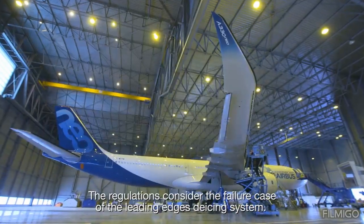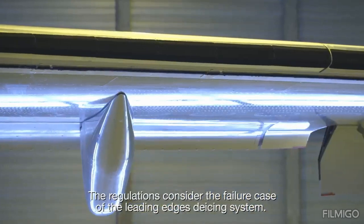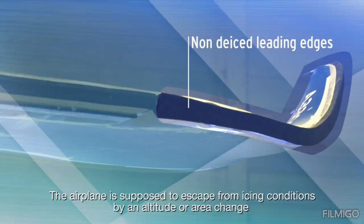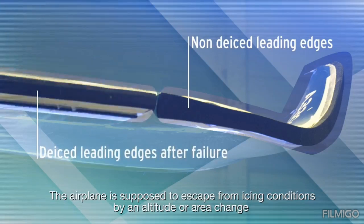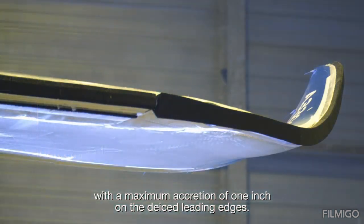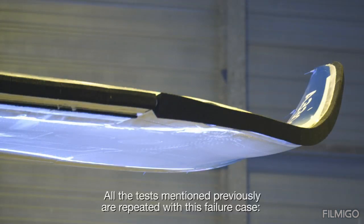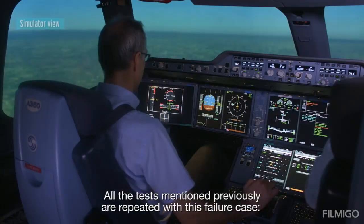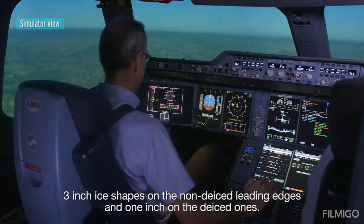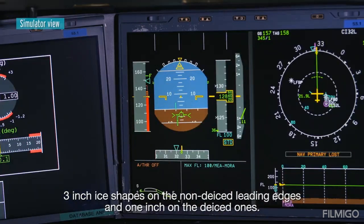The regulations consider the failure case of the leading edge's de-icing system. The airplane is supposed to escape from icing conditions by an altitude or area change with a maximum accretion of 1 inch on the de-iced leading edges. All the tests mentioned previously are repeated with this failure case: 3-inch ice shapes on the non-de-iced leading edges and 1 inch on the de-iced ones.